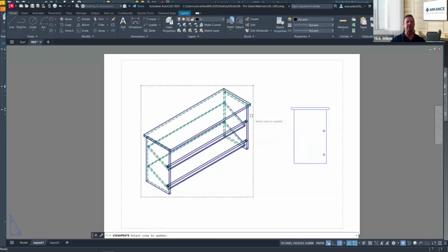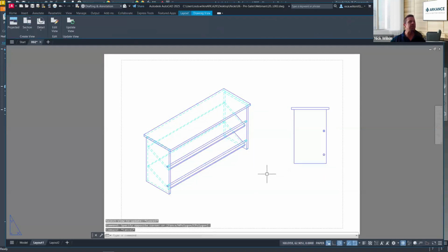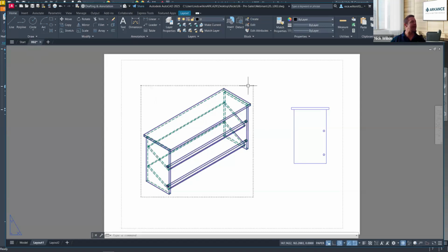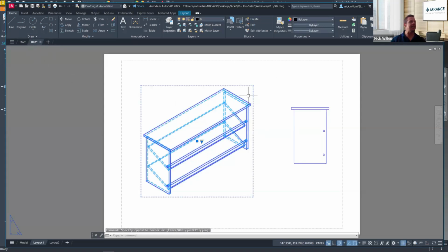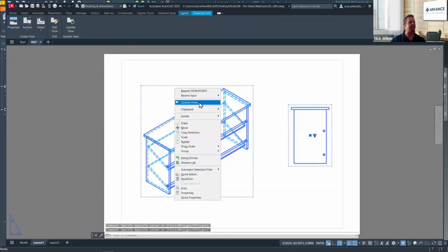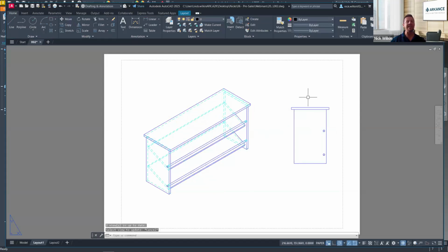Then it even asks me to select the views. Select the views. And what does AutoCAD say? The view is up to date. All right, so here's the trick to that. If anybody's found this to be an issue, it will update. But here's what you need to do. You need to actually close this drawing and reopen it. And included in that, you might actually have to edit it and update the view manually, right? So you might have to tell it where that IPT is found.